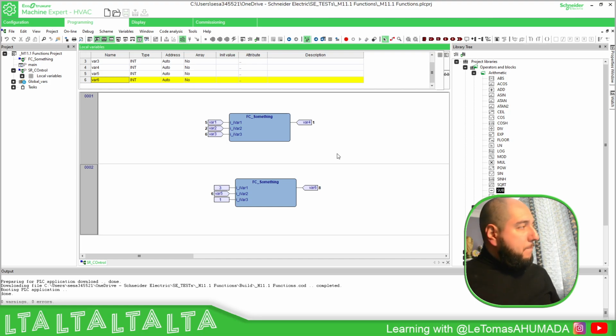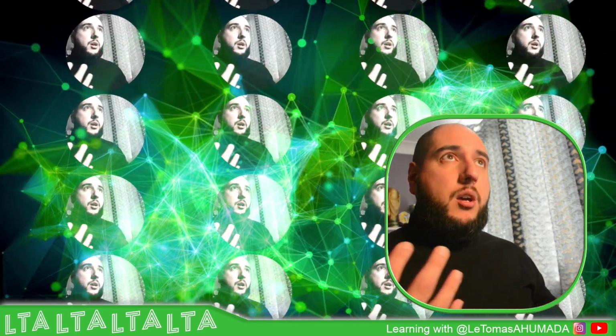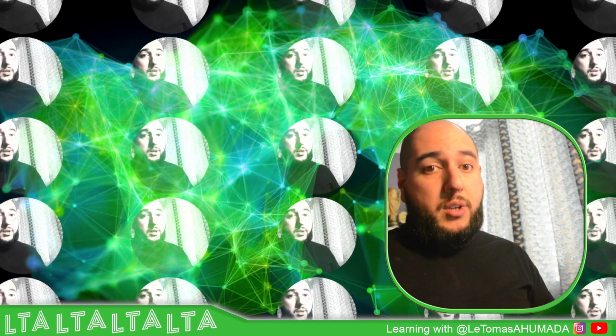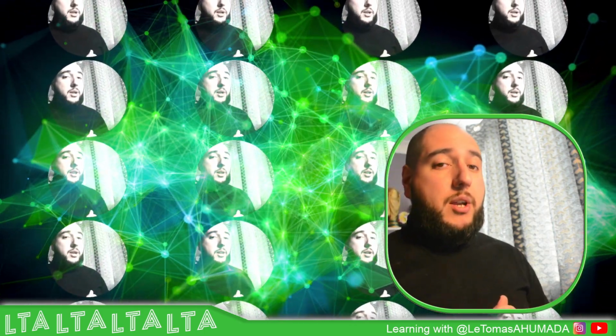So this is how you can create functions inside the EcoStruxure Machine Expert HVAC. Just add functions and then you just need to name it and define which is the code that you want. It's very straightforward how to create, and the important thing is which are the things that you want inside. You need to remember that you want to have just one output and you can have multiple inputs to make the code. So this is it for the creation of functions inside the EcoStruxure Machine Expert HVAC.